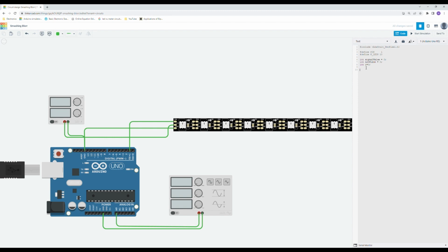Okay, so first thing we have to do in our code, so this is just the initialization part. Let us start and create the object for the LED strip. So Adafruit_NeoPixel strip is equal to Adafruit_NeoPixel with the following parameters. The first one is the number of LEDs.